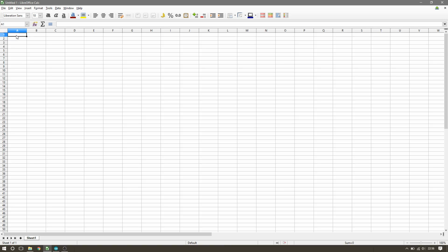So I am going to sample all 6 ADCs, 2 of which are being pulled low with 100k resistors, and one of them going to a 3.3 volt reference. Even though this ADC is running off a 5 volt reference, it's just plugged into a 3 volt reference from a different Arduino, just for a sanity check.